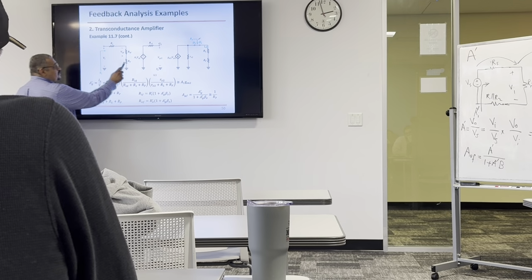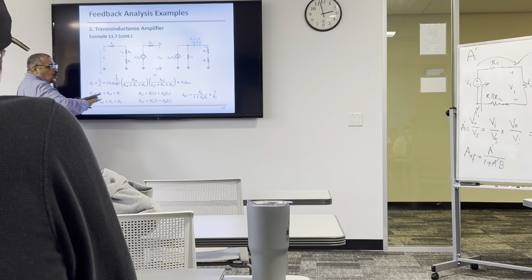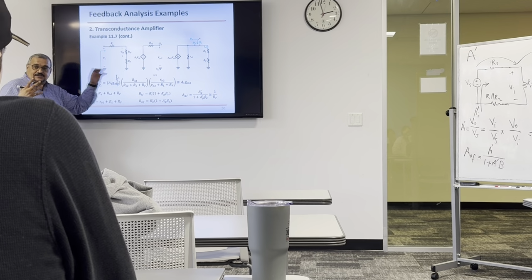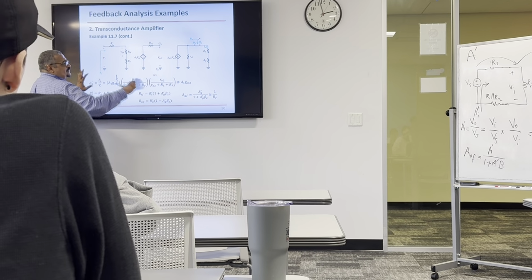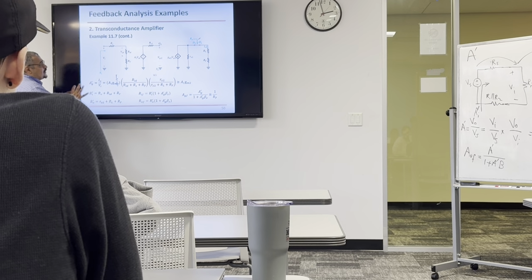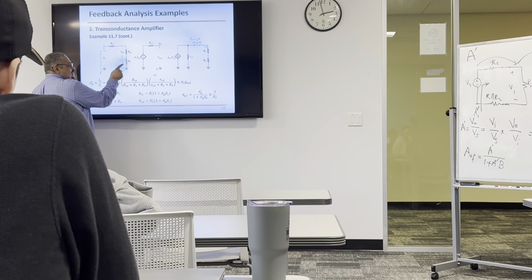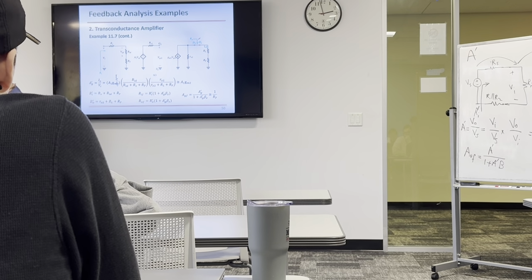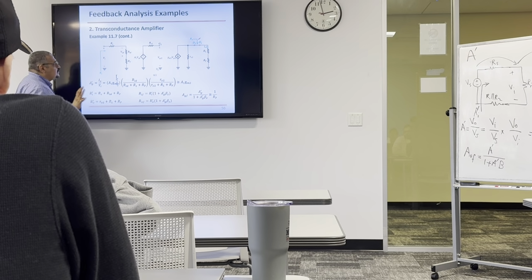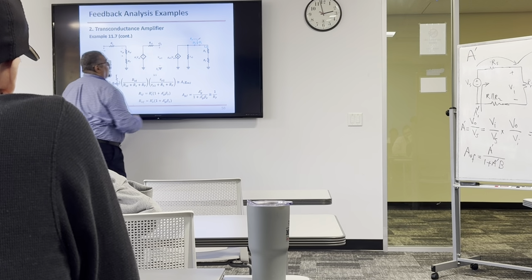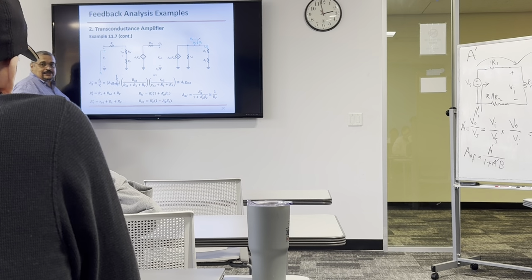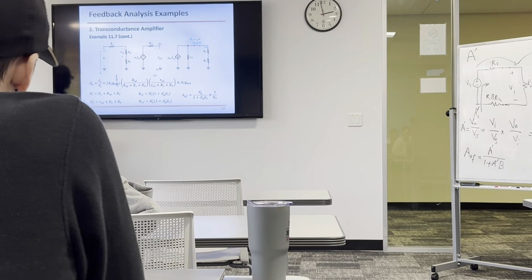Okay, so RF is here at the input. So we broke the feedback, but we kept its effect at the input and output. This is the main idea. So we came up with a new amplifier that doesn't have feedback. But that amplifier is not this and this only. No, it has this and this. So it's not A anymore. It's called A prime. It's a new amplifier, but doesn't have feedback. Now we need to find A prime. Now we have RS and we have RL, so we have to include them in calculating A prime, RN prime, and RL prime.